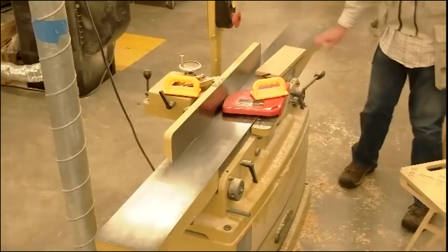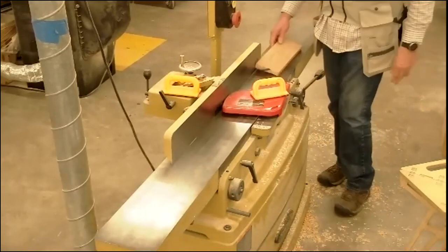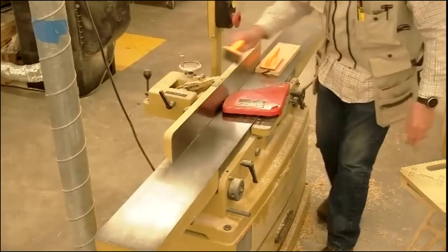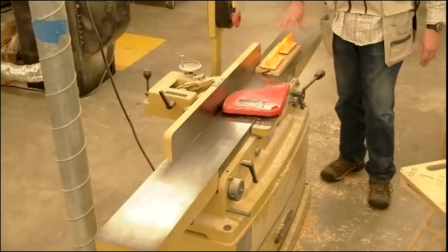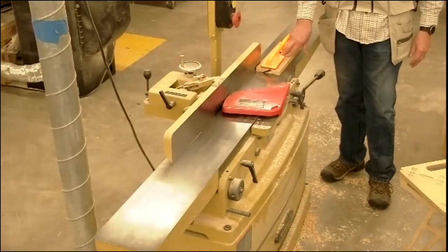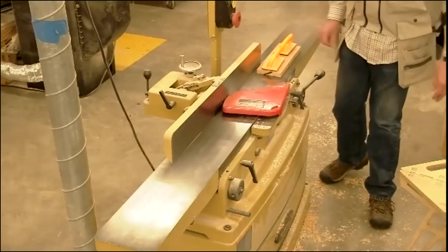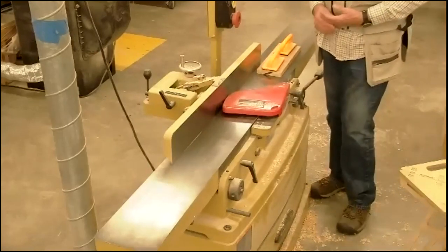All right, I've got it set there, right? I don't have it set so it's rocking on the table. I have it set so it's sitting on the table. So the way you place your pads, and you will always have to use push pads on the jointer, especially when it's face down. You can never put a bare hand on the face of the board when you're jointing the opposite face. It's a bad situation. Where you place your hands and how much pressure you put on the board are important.